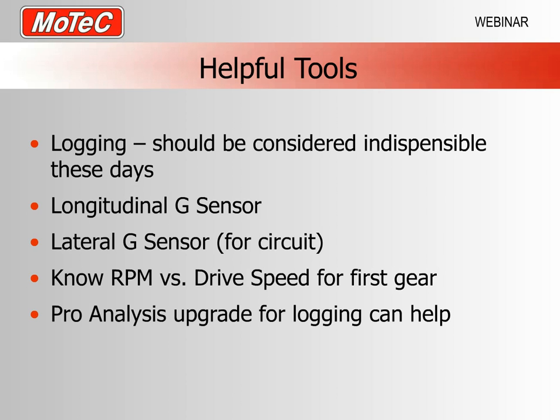Helpful tools. Logging is the first one, and I say helpful tool, but it should be considered pretty much indispensable these days. If you're trying to set up all of these wonderful functions on your Motec ECU and you don't have data logging, I would suggest that you are not doing the best job that you could. The driver cannot remember 64 channels at up to 200 times a second and how each of them compare. The ECU can with your data logging, or even if you're lucky enough to have a dash logger as well.